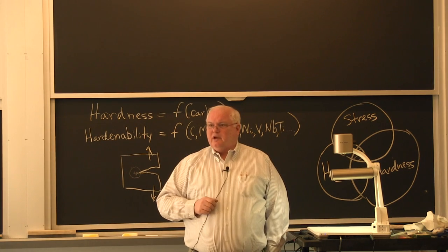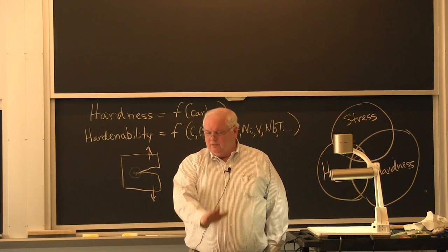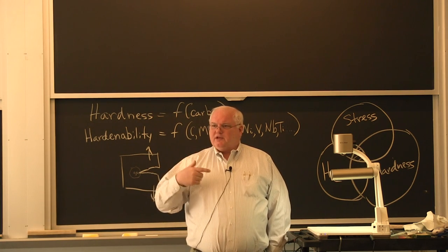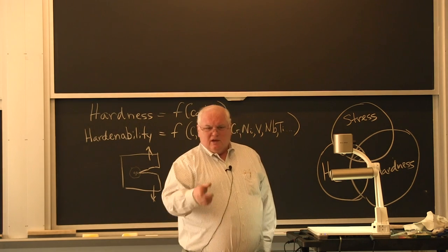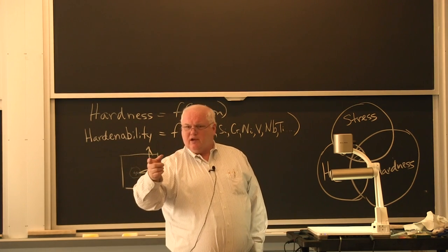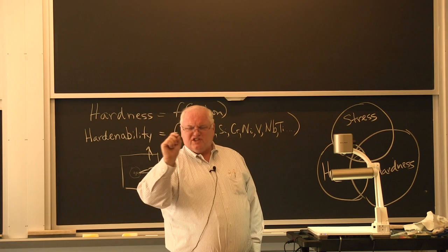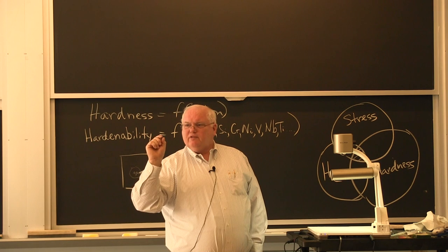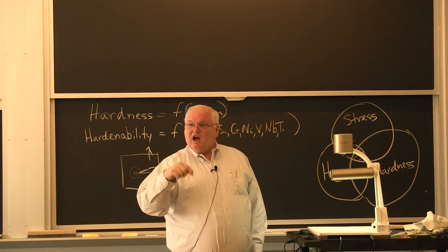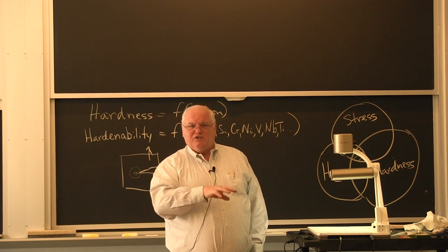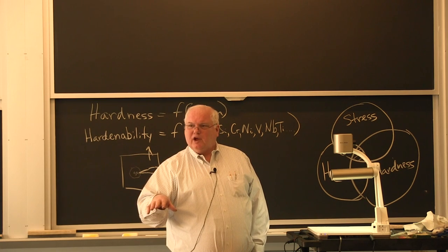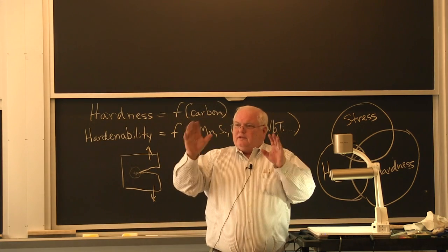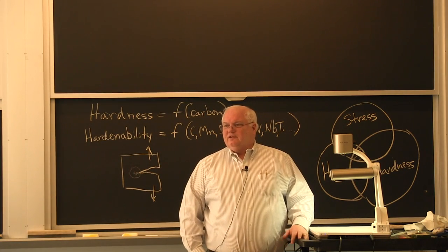Mild steel, not a big problem. You can use cellulosic electrodes. You're welding a regular old pipeline, root pass goes in as 6011, cap passes go in as 7018. Those were the same diameter of steel rod, but the 7018 was much thicker on the flux. That's because it contains iron powder in the flux, and it gives you a higher deposition rate. You can weld faster with 7018 than 6011. The type of weld, you're not welding on something fancy, right?